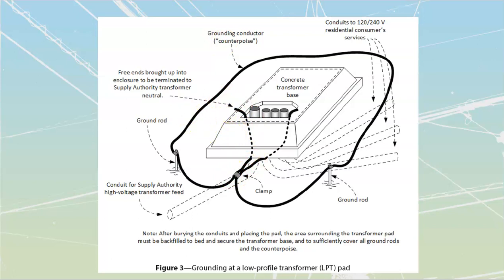The coil of heavy steel cable that you will get will probably be too long for what you need inside of there. What you're supposed to do with that extra length is just take that length and loop it like that and then stick a tie wrap around it. Bury that at the back end. It's the standard way to deal with excess length. Don't cut it off of these ends over here. You'll have to apply a couple of heat shrink boots over top of those ends. They come with the kit as well. And then when Hydro shows up, they drop that on there. They will pull in the high voltage lines. They will pull the low voltage lines.